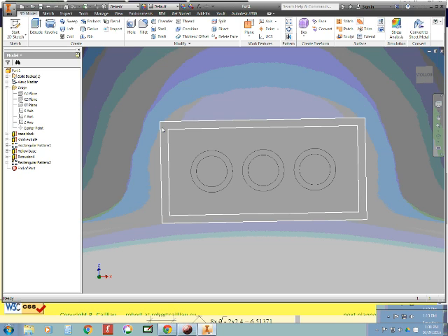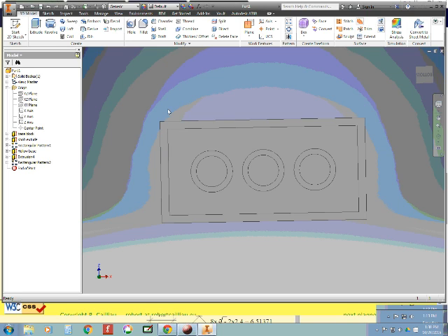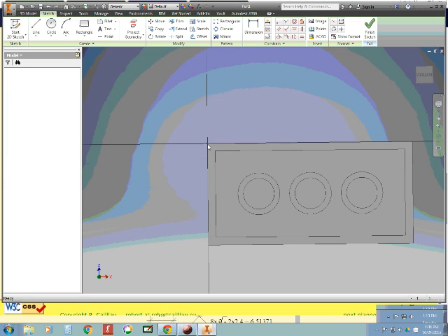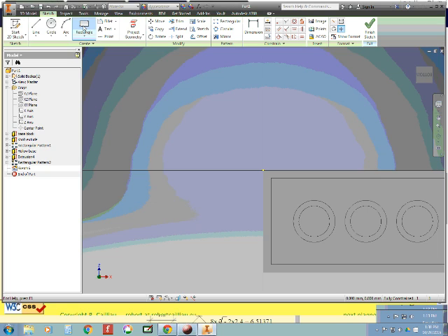I'm not sure that there's a huge difference as long as you're extruding them in the right direction. So once again, we want to right-click on this and choose New Sketch. And we're going to use the Rectangle tool. And up here, I'm going to make it 0.6 wide. Tab to go to the other dimension by 0.3 tall.